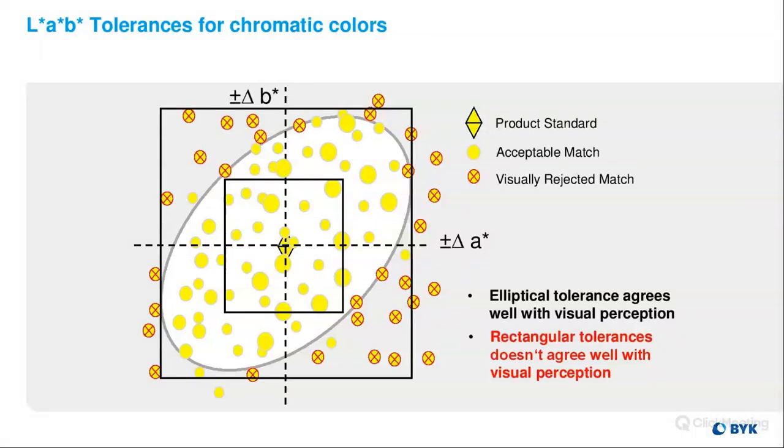But if you're going to do it correctly, you need to have good samples, borderline samples, and bad samples, based on what your visual idea is for those. Then take those samples, measure them, and look at the different color equations to see which one matches closest to your visual perception.